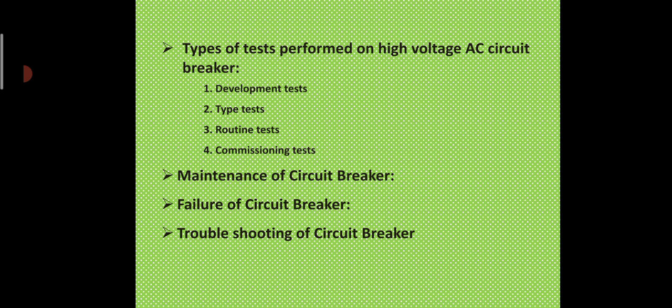Now, maintenance of vacuum circuit breaker. The steps of maintenance of vacuum circuit breaker are operational checks, general inspections, cleaning, opening devices, insulations, circuit breaker enclosure, main connection, secondary wiring and fuses, mechanism, auxiliary switches, indicating devices, shutter, switchgear, isolating contact, vacuum interrupter, isolating and earthing switchgear, earth connections, overload devices and relay, instrument protective transformers, control relay or contactors, etc. These are the important steps in maintenance of vacuum circuit breaker.